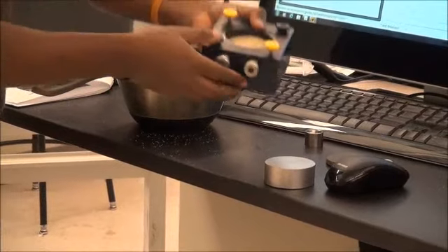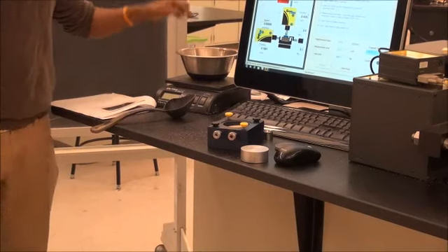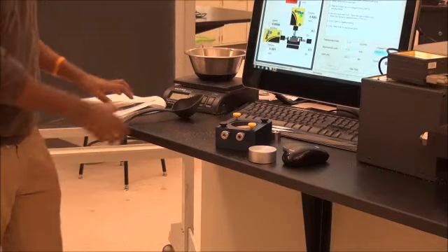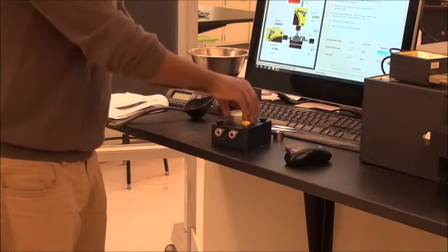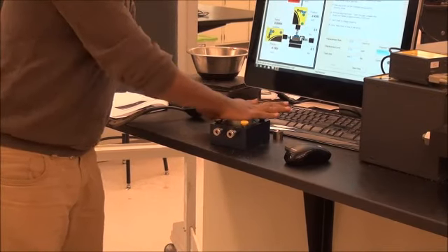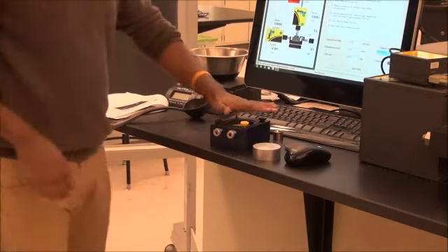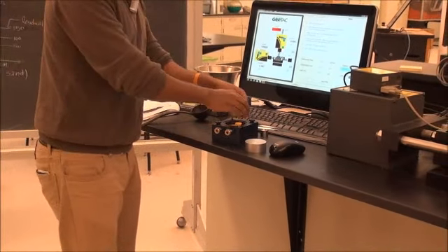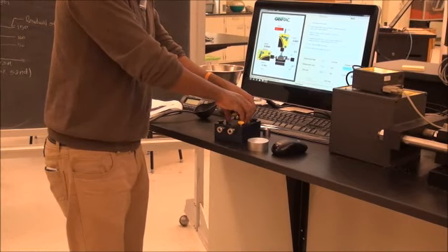Once it reaches that mark, you have to measure the remaining soil in order to know how much soil you added. Then we have a spacer. You have to level it and tamper it a little bit so that you have a well-trimmed sample. Then on top of that, you put your porous stone carefully on that leveled surface.